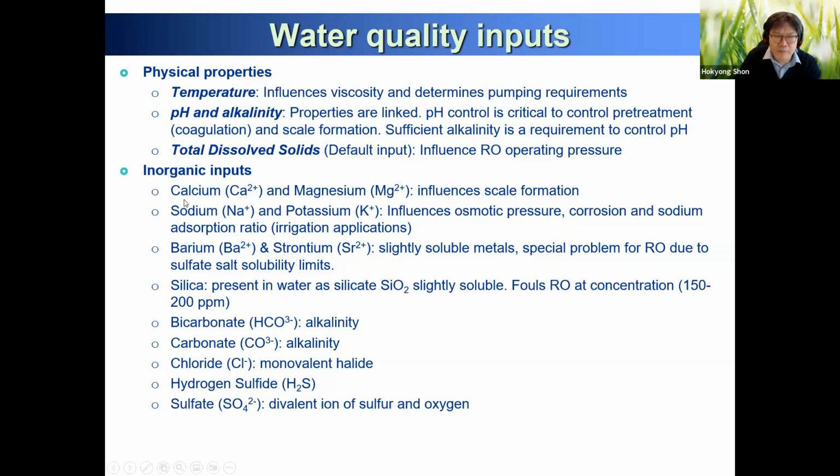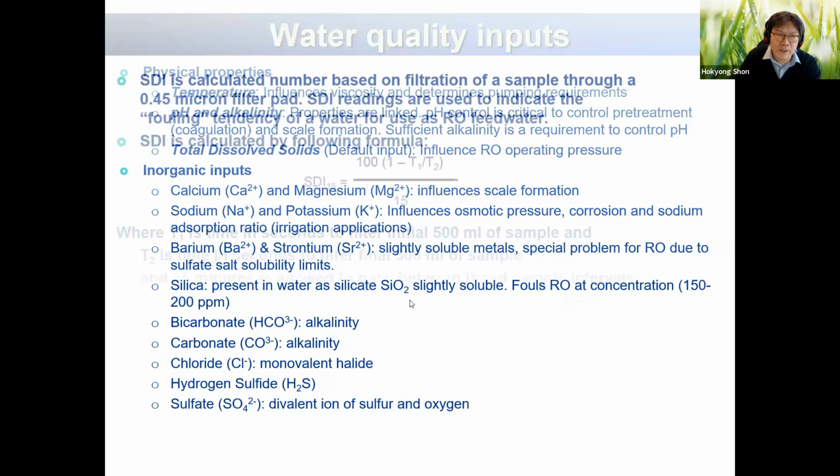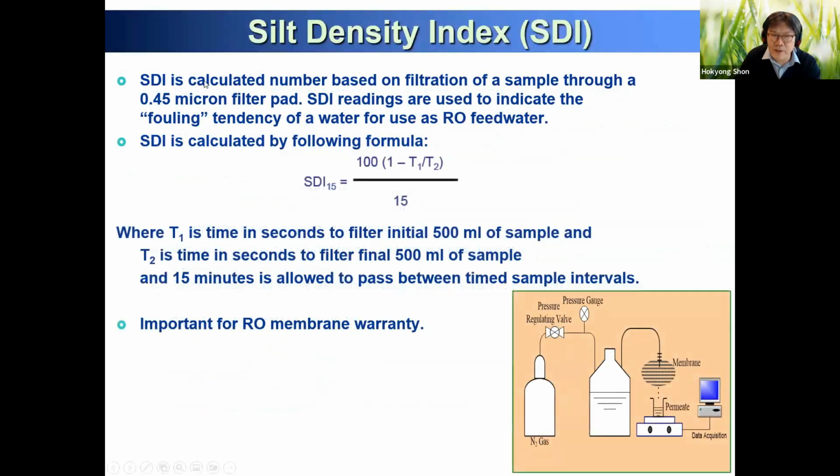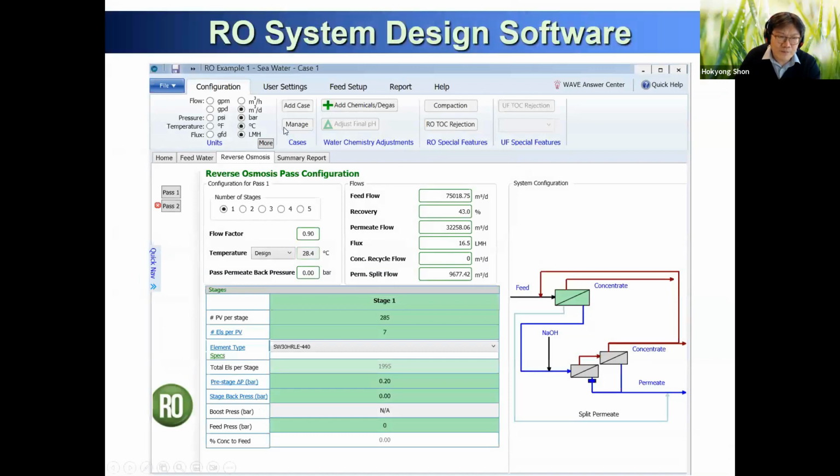Also the inorganics: calcium, sodium, barium, silica, bicarbonate, which we already discussed during water quality. Also SDI, which we also discussed, because SDI has to be given to your software. That is the minimum feed water information you need to include in the software system.